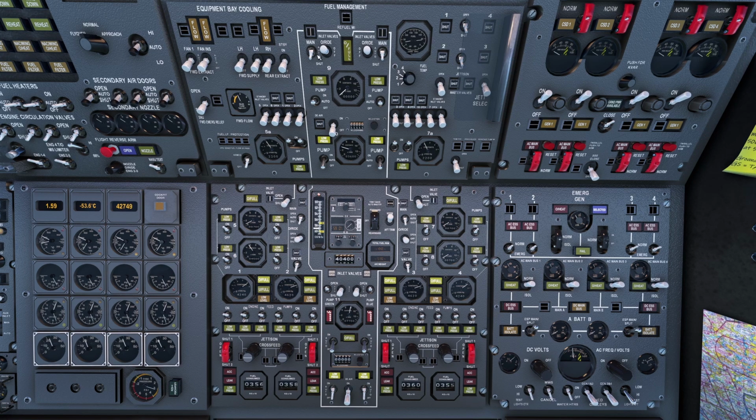Tank 9 is empty, so I can close those pumps. They will not have an effect anymore. I'm going to close the inlet valves just to be sure that no other fuel is flowing. For the moment, we are trimmed correctly. Approaching 1.7, where we're going to reduce speed, the thrust without the afterburners. Remain on 100% and continue our climb to 50,000.